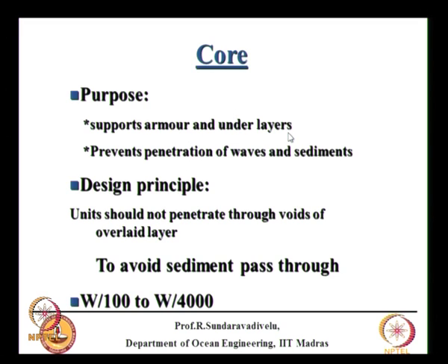We have given some general guidelines, but there is a basis also for this, that is what I am explaining to you. If you do a major project, you have to calculate the armour size, that you cannot do with a sieve, you have to do separately. So the core layer supports the armour and underlayers, and prevents penetration of waves and sediments, that is the purpose. Design principle: the unit should not penetrate through the voids of the overlaid layer.